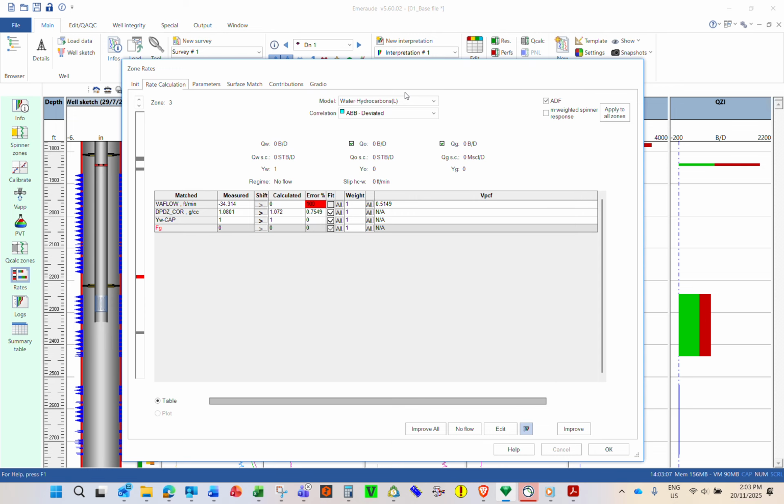So, yeah, remember yesterday, if it is liquid, then we'll be using ABB deviated correlation to get the VS. And the hold up is, yeah, you can have the hold up here from both capacitance and also DVDC. So you make those two hold ups and average both of them and then calculate the slippage from ABB.